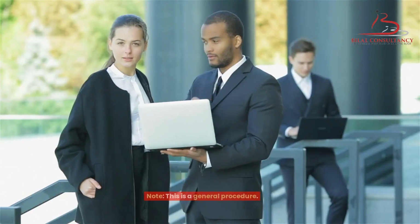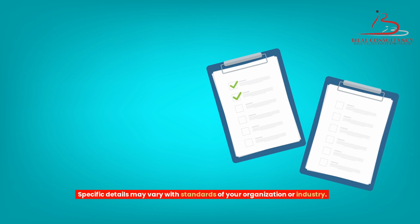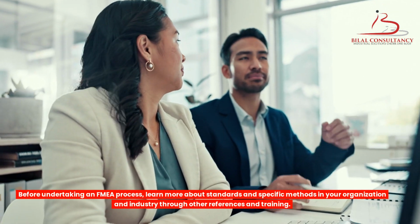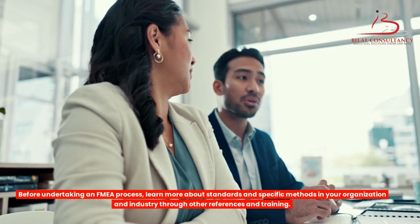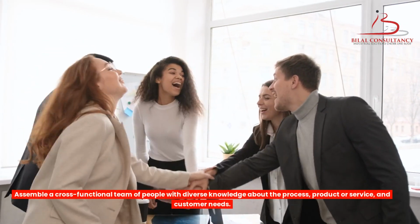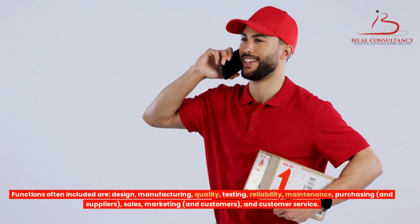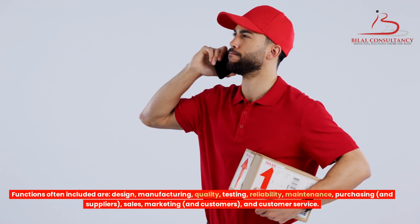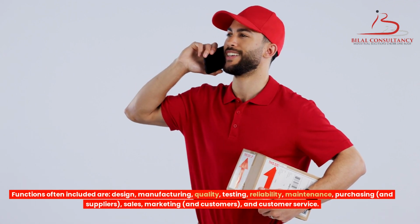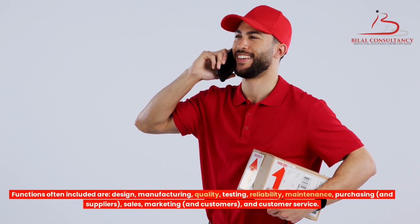FMEA procedure. Note, this is a general procedure. Specific details may vary with standards of your organization or industry. Before undertaking an FMEA process, learn more about standards and specific methods in your organization and industry through other references and training. Assemble a cross-functional team of people with diverse knowledge about the process, product or service, and customer needs. Functions often included are design, manufacturing, quality, testing, reliability, maintenance, purchasing, and suppliers, sales, marketing, and customer service.